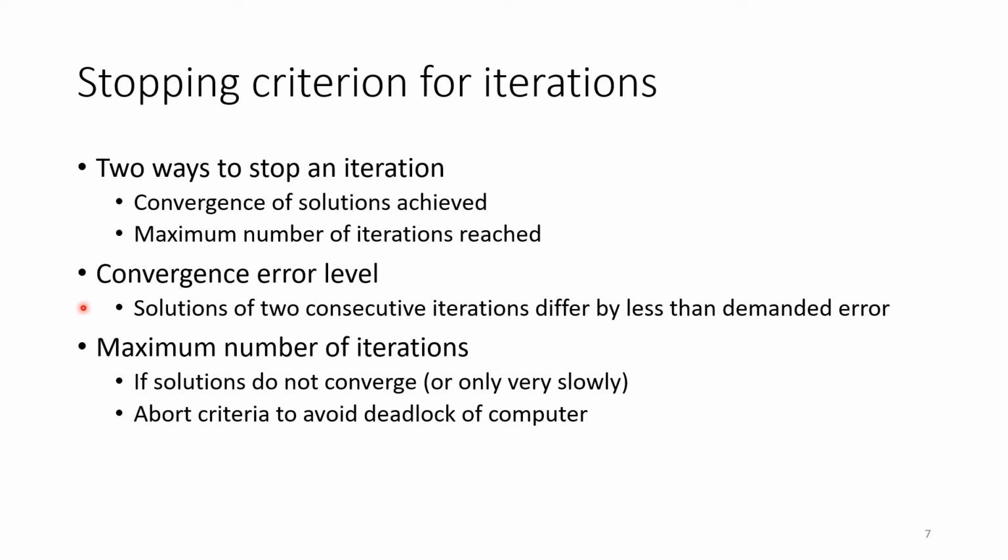Right, but those are two parameters you can provide to the groundwater flow module in GRASS GIS, and you can vary those parameters and see how it influences your result, which is very interesting and very informative for you to learn, to understand how those kinds of solvers work.